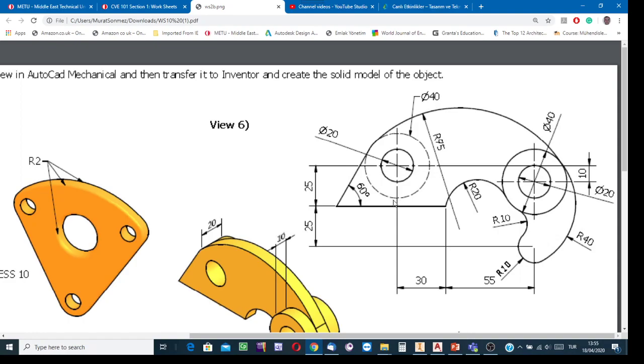Here, see, we have some tangent lines, but some of them have only one tangent point. For instance, this one, you see a circle arc. It is tangent to this, tangent to that. It has two tangent points. And we know its radius. So for this boundary, there is no difficulty. If you selected the classical method, select the Tan, Tan, Radius option from the list.